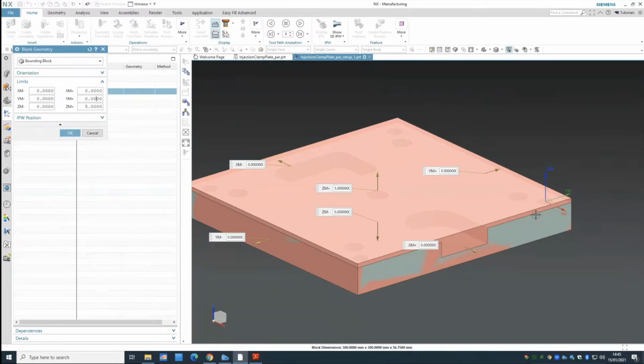The best example: if you have a MacBook or a Surface laptop, you can see they have a really clean lid, made of aluminium, and they've used face milling to reach that really good level. If they wanted to operate on the Y, you could add it into the Y as well, so you can do operations on the sides. You don't have any operation in this one, so just keep it 0.